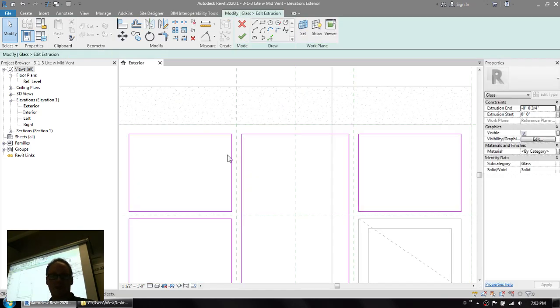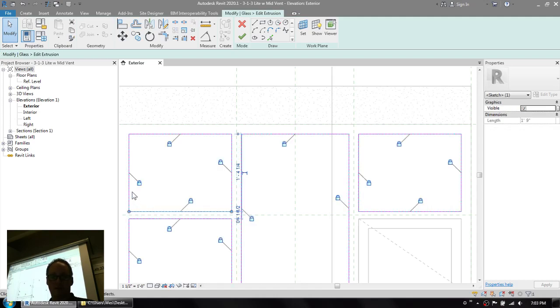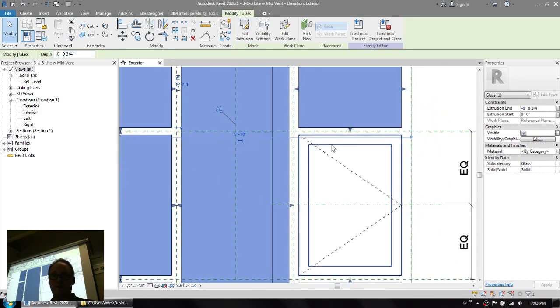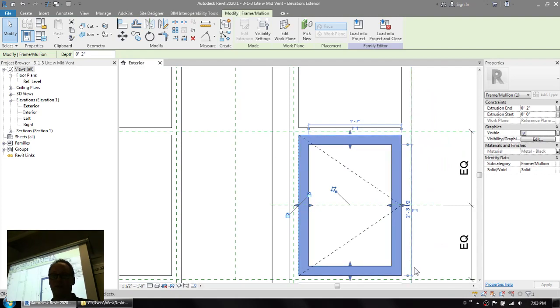So these sketch lines in the glass are constrained to the window frame, just as the vent frame over here, its outer edges are constrained to the vent frame. Now, the second bullet point there is constraining lines in a sketch to reference planes contained inside the sketch.